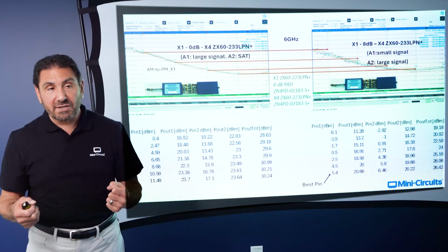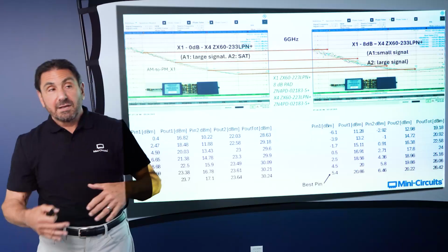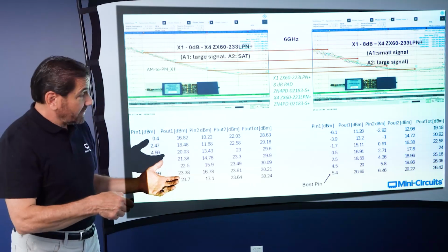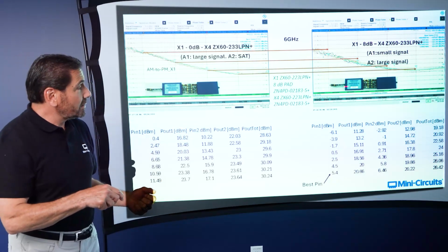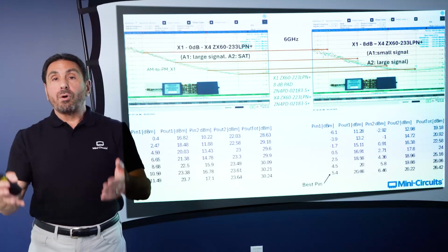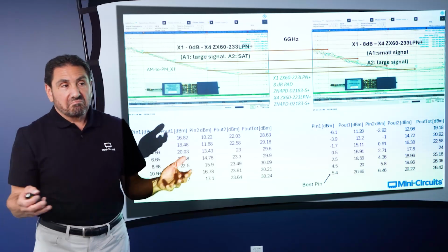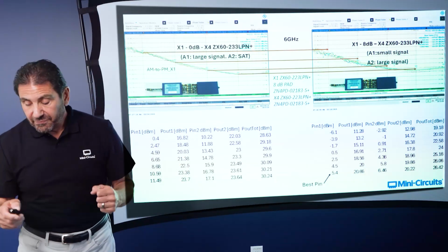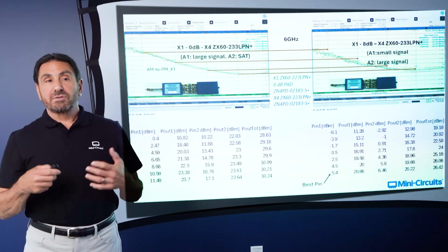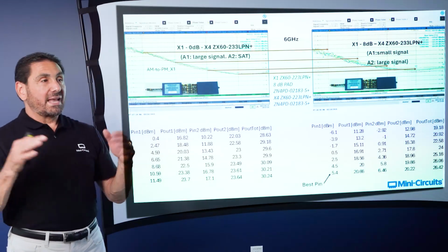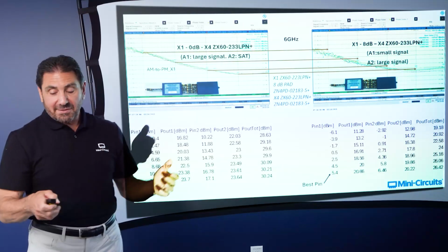And I did that by careful selection of input power into my first stage and by controlling the input power into my cascade. So if you really think about it, if you can have an arrangement like this, if you can afford the power, the DC power, a single driving a combined will always be better than a single driving a single. And if you select the right input powers and you select the right padding. So it's a great way to show how you can demonstrate, again, a wideband amplifier cascade that achieves optimum additive phase noise performance in your system.